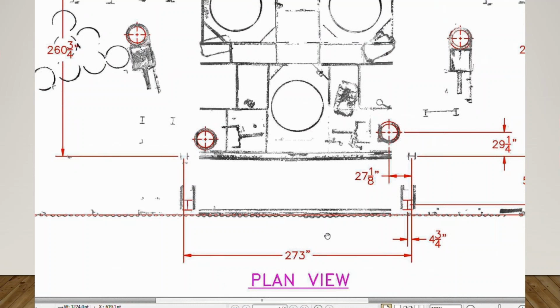In industrial situations, the reason this works is I turn down the level of points each scan takes, so that each scan takes about 2 minutes. I turn off the color imagery, because the scan can take 2 minutes and the color imagery can take 5 minutes. So I turn off the color pictures and take the laser scans. Now I can take between 50 and 70 scans per day.